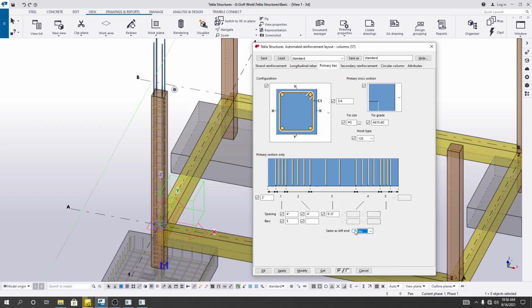Okay, so I'll just click yes, right, and here bar 5. Okay, also you can ignore that. Then if I click here modify. Okay, if I just click here modify, now see, and sorry, I have just provided here 8 feet 0 and 8 inch. I'll again click here modify. Just see, here we have provided reinforcement detailing for our column the right way.